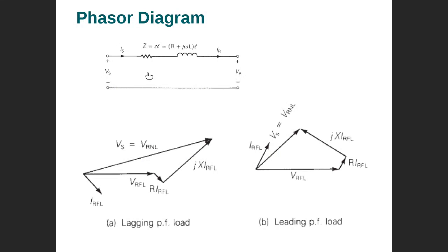Okay, now relating to the phasor diagram, for example, you have VS and VR. Remember, this is a short transmission line because there is no shunt. Now, if the power factor is lagging, you can draw VR full load here. You start with VR full load, and then it's lagging or leading. They will say lagging, therefore you will draw the current lagging the voltage. So you will be given VR full load and the current, whether it is lagging or leading. That's the whole information.